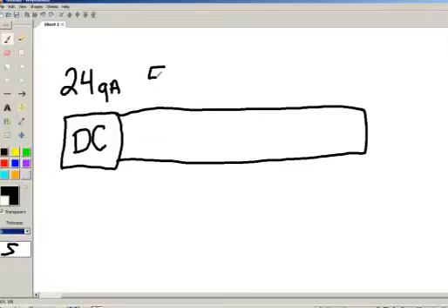I'm going to say it's 24 gauge cable, and your ohm meter reads 51 ohms, and that equates to 1,000 feet of loop resistance. Now that ohms to distance equation is found in the HST under the F1 display key. So this is what it would equate to: 24 gauge, 51 ohms means the short is 1,000 feet away.